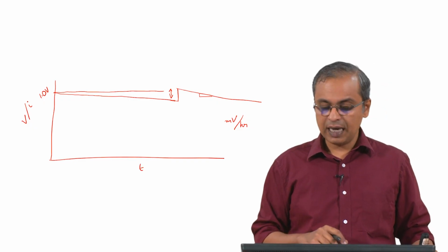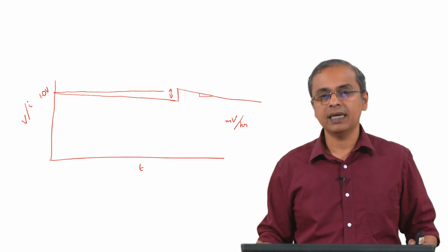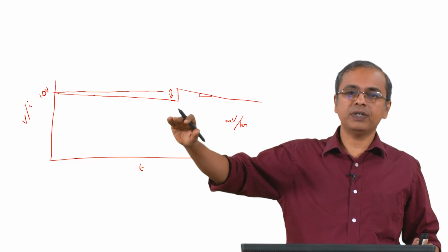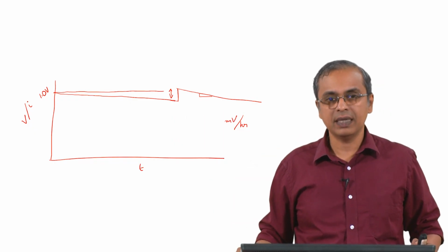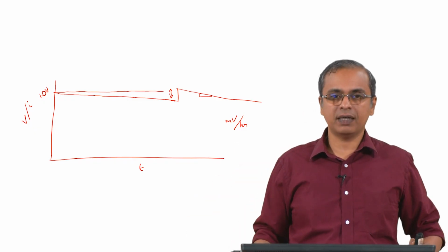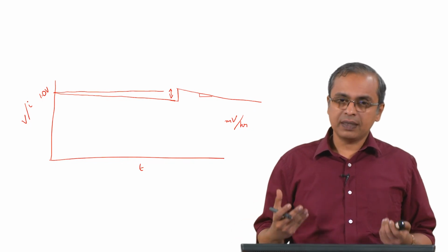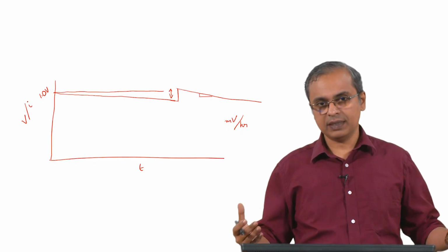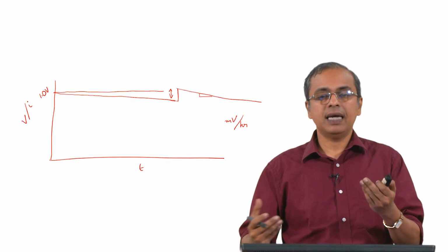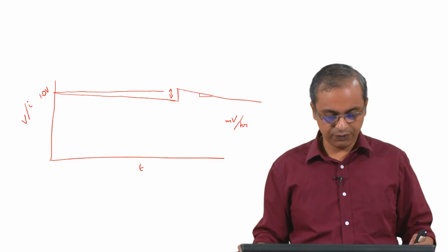as they characterize these devices. It also turns out that this rate of degradation, the slope that I have just shown you on this slide, can actually vary significantly with time. In other words, you may have a very gentle slope in the first say 500 hours of operation, and then you may have a much steeper slope from 500 to 800 hours of operation, and it may just precipitously drop off after 800 hours of operation. So, this is not even a constant slope. A lot of research is done to understand what is causing that slope to be a certain value for the first 500 hours, what is causing the slope to change between 500 and 800 hours, and what is causing the slope to completely collapse after 800 hours of operation. That is just to give you some idea of the kind of work that is done.